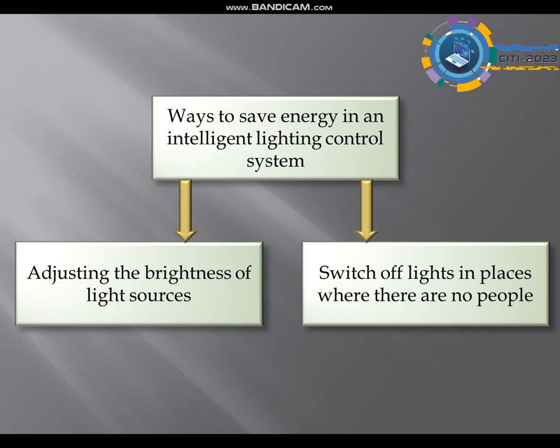The use of fluorescent lamps in lighting systems with a control system faces a number of challenges. One of them is the short-term preheating of the lamp electrodes before switching on. Its presence creates a delay before switching on. This should be taken into account when designing intelligent lighting control systems. Therefore, experimental studies were carried out to determine the duration of the preheating mode of fluorescent lamp electrodes.